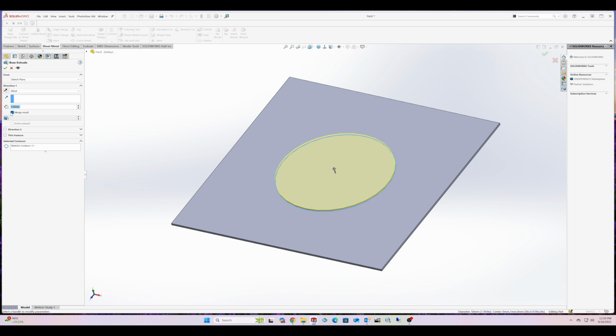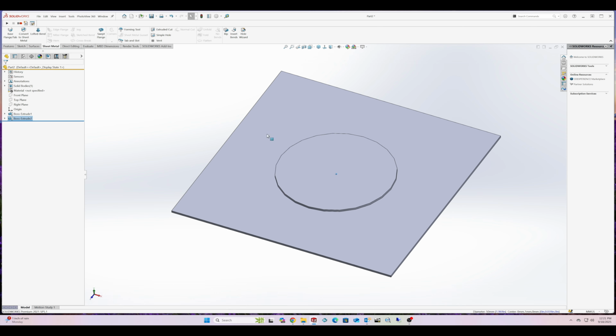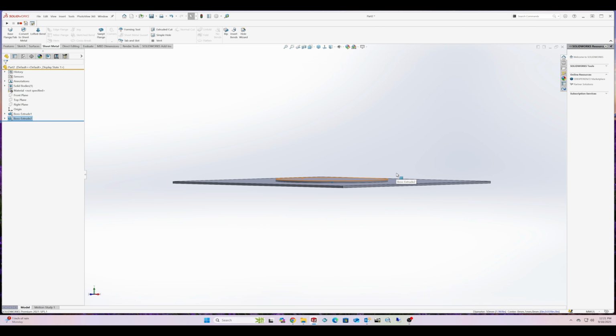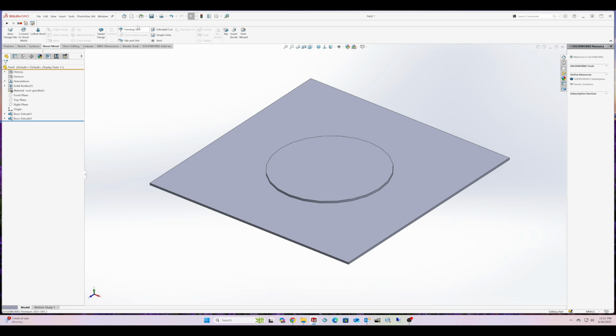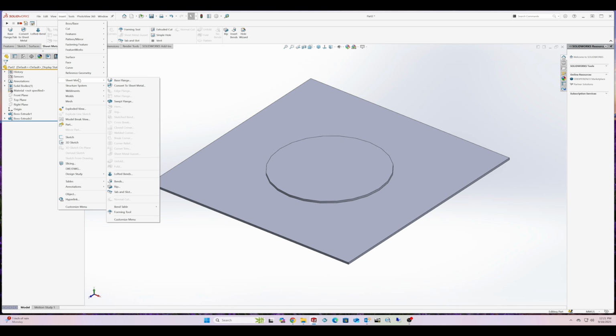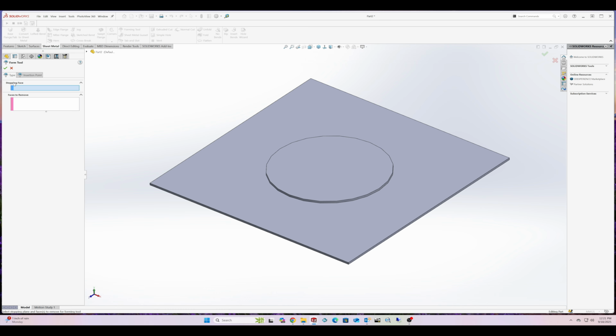And I'm going to give it a little bit of a taper just so you can visually see that. When I'm dealing with forming tools, I want it to be able to cut. When I'm putting it in my part, I want to have that profile on the front, but when I look at the back side of it, I'm also going to have an indentation there to where that form tool will push through. That way, when I'm sending out DXFs to my NC programming, I have that in that 2D flat DXF, depending upon what surface it picks, I've still got that round on there.